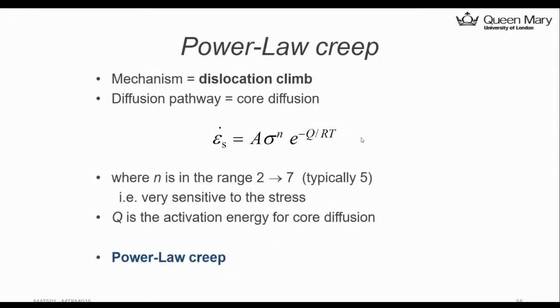And the equation for that, we have shown you several times, and that's the most important equation in creep. Okay, we repeat that again, where n is in the range from 2 to 7, typically 5. Okay, and it is very sensitive to the stress, because that term is a power law. It really makes the stress dominate the whole term.